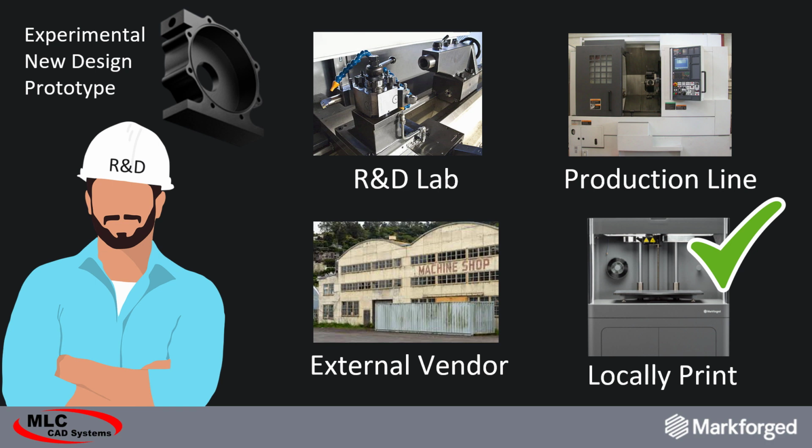But if you can print it in a strong functional material, you can actually take that part and not just do fit and function. You can actually start testing it. You can actually start running it in the R&D lab. You can check and see if it's going to give you the results that you need without having to fully tool up beyond simply a toy or a placeholder that you might get off of a low volume or low quality machine.